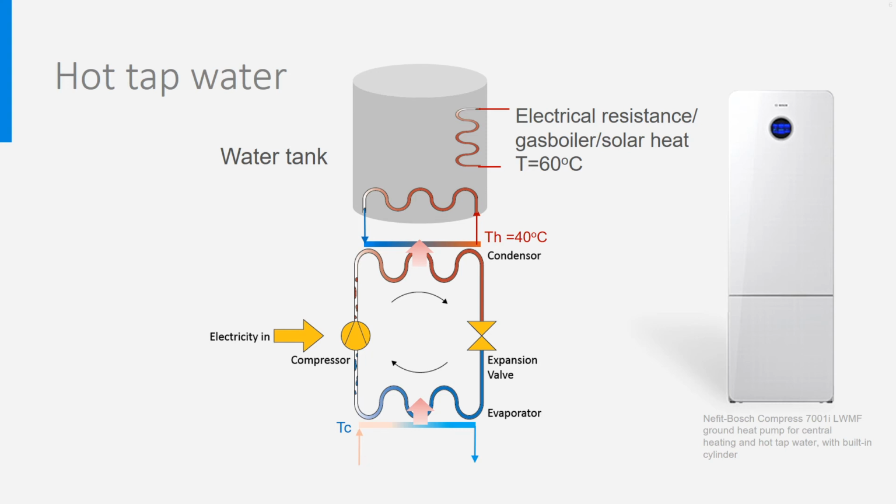Heat pumps for hot tap water are generally coupled to a cylinder in such a way that the heat pump can take its time to fill the cylinder with hot tap water while having a limited power. This will save costs. However, such a cylinder will cause additional heat losses through its casing, also if it is well insulated.